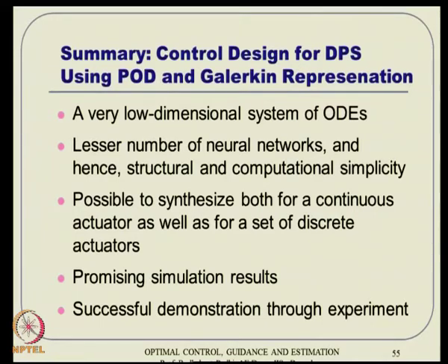So, now going back and thinking a little bit, the procedure is good as long as the snapshot solution is good. Now, how do you generate a good set of snapshot solutions? That again depends on the intuition, depends on the prior experience, depends on several ad hoc procedures. And then, as I told before, the people have proposed a different way of doing things, something like adaptive POD and dynamic reoptimization of PODs and things like that. That means you do not generate the basis functions once and then keep on working on that. You can have a procedure where the basis functions themselves get refined as you go along, because you will have better and better snapshot solutions as you go along. So, those kind of ideas are available in the literature.